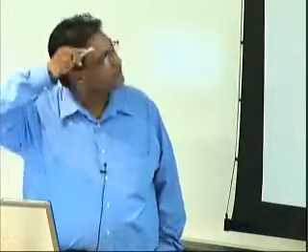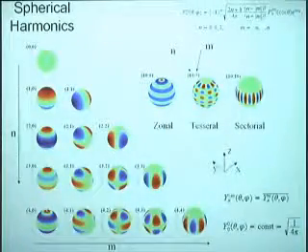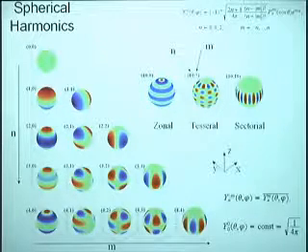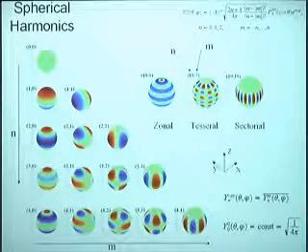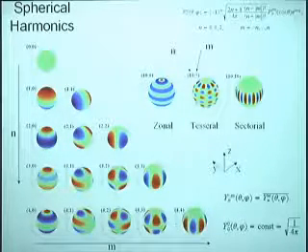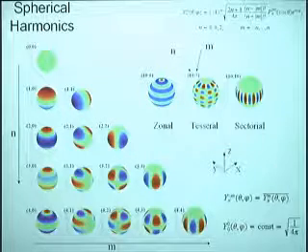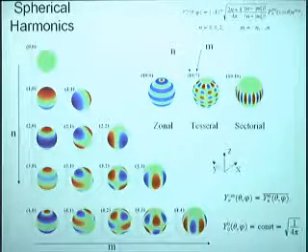For Fourier series you have one frequency parameter. For spherical harmonics, you have two frequency parameters. In one direction you increase the frequency this way, which is north-south along the latitude. And as you increase the second index, the order of the series increases along the azimuth. Any function can be expanded in terms of spherical harmonics. Because with the spherical array you know the weights corresponding to a spherical harmonic beam pattern in a particular direction, you can now automatically compute the beam pattern for any particular shape you would like for the beam.